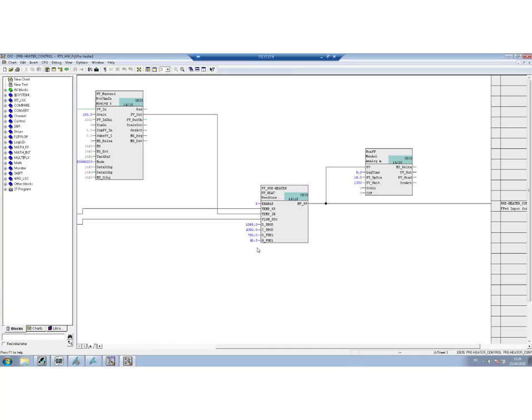If we look at the feed forward, I've written here a block, an FB, that implements this feed forward. It takes the temperature set point at the output, and you have measurements of the input temperature and the product flow, right?